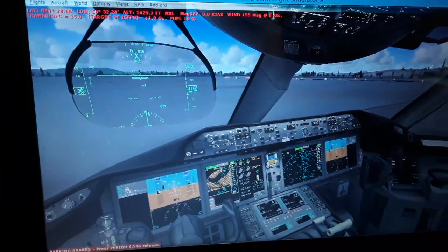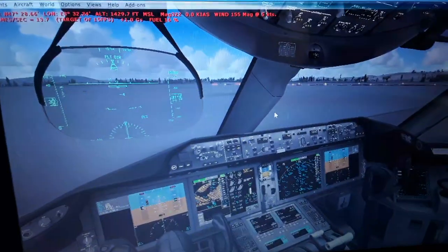We also have the navigation display, that displays the GPS inertial reference position of the aircraft, its coordinate position, latitude and longitude. We can align with the flight management computer, the inertial reference system panel, and the overhead panel. I will show you later how to do that. We also have the display of the magnetic north pole and the geographic north pole, and the magnetic variation depending on where we are in the world.